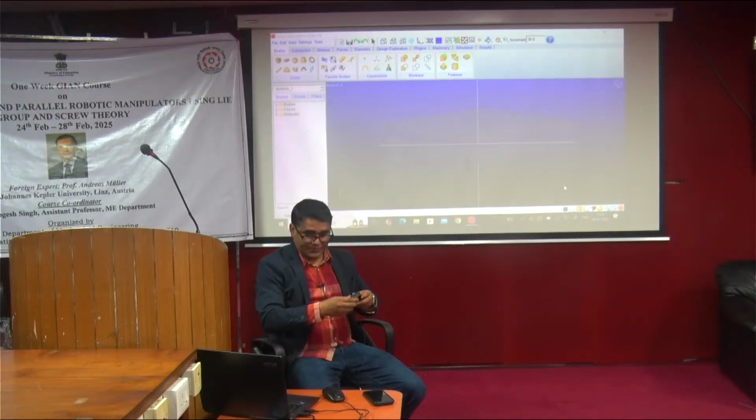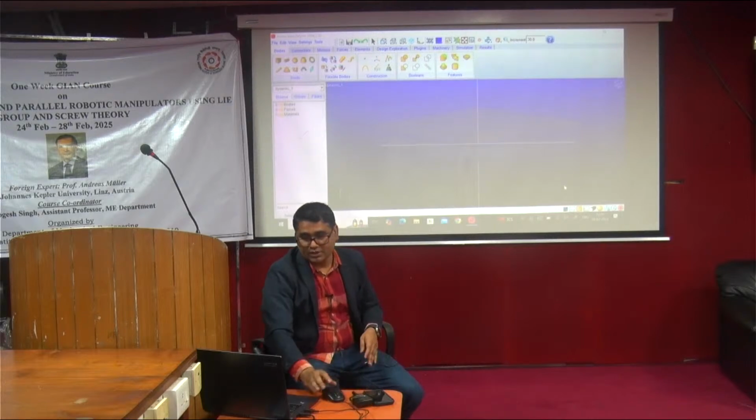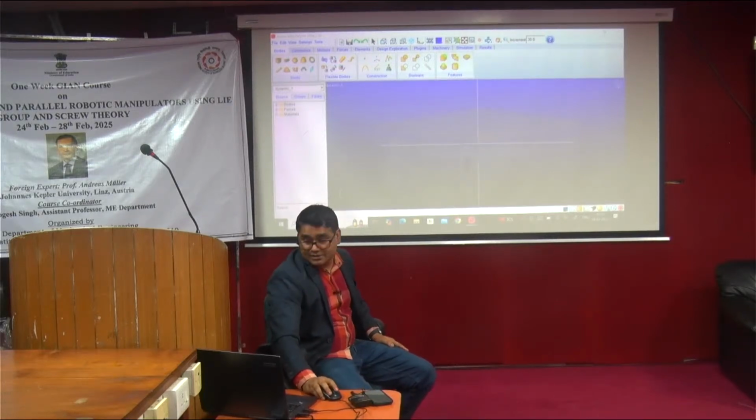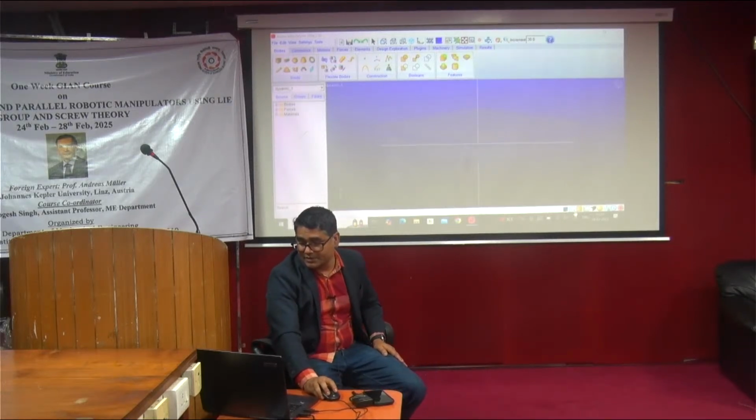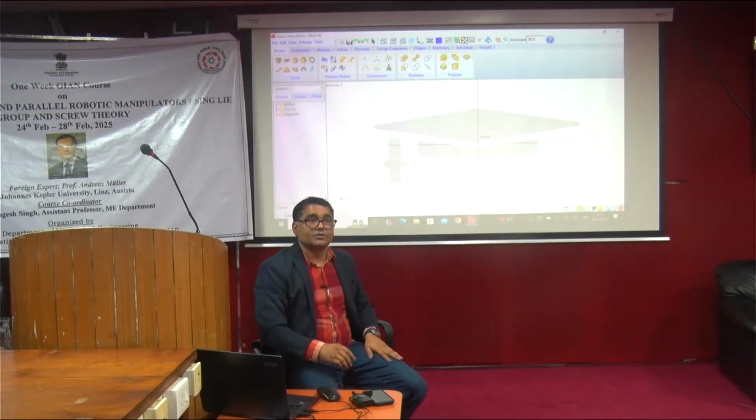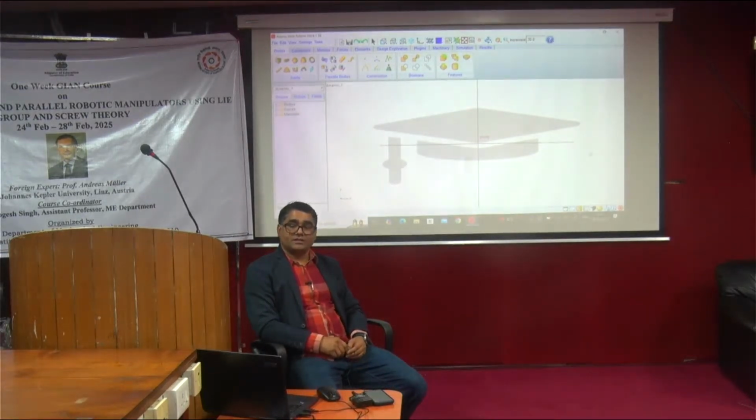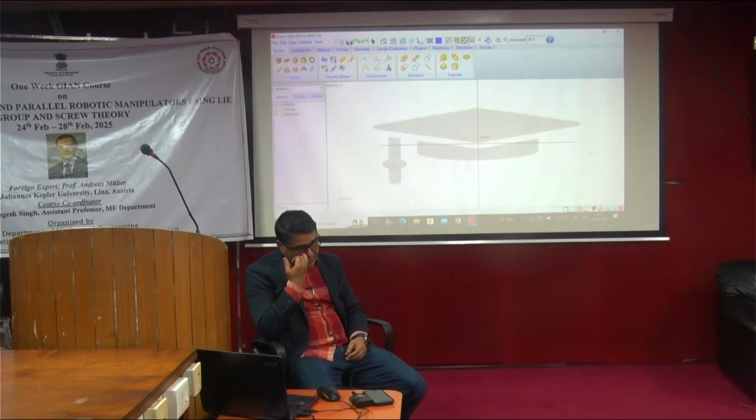Okay, so now we will see how to do this particular job. In this particular manipulator, we are going to deal with the dynamic system modeling. So in the dynamic system modeling, what is the requirement? As we have seen in the lectures, the dynamic equation of motion is required. We have to define the mass, Coriolis component, gravitational component, and then do the modeling.